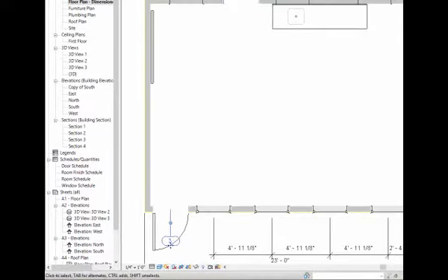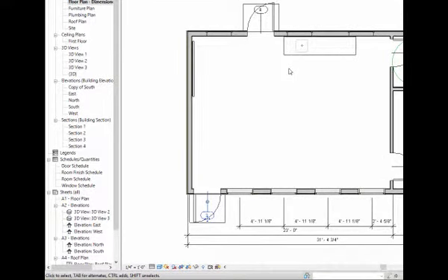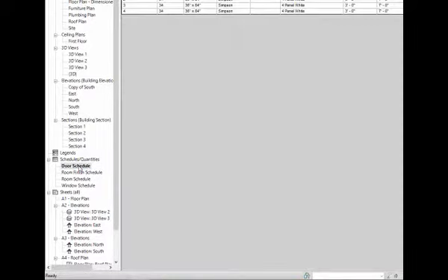Okay, and it's reporting some value. And it turns out you can control what value that is. Whether you want to see the ID of the door, whether you want to see a textual description of the door, or whatever it is. Let me go ahead and close everything that's not shown. And I'll bring open that door schedule. And I'm going to go through and just tile those so I can see them both.